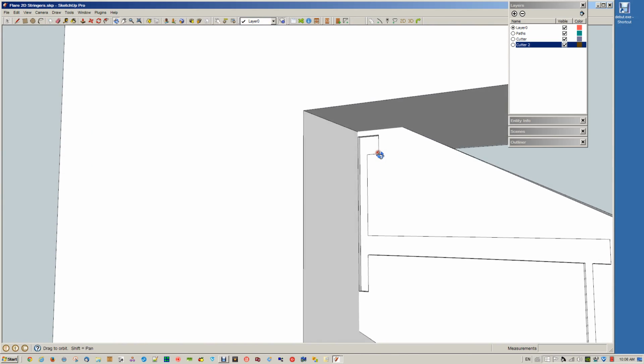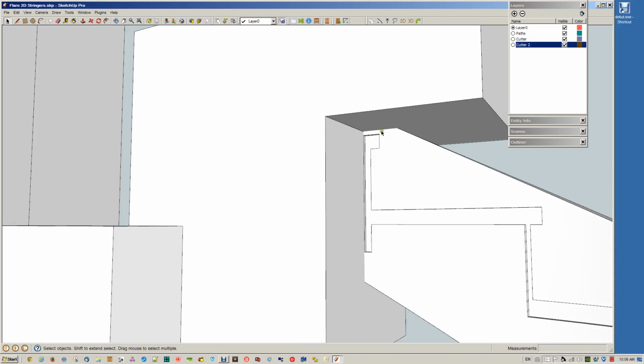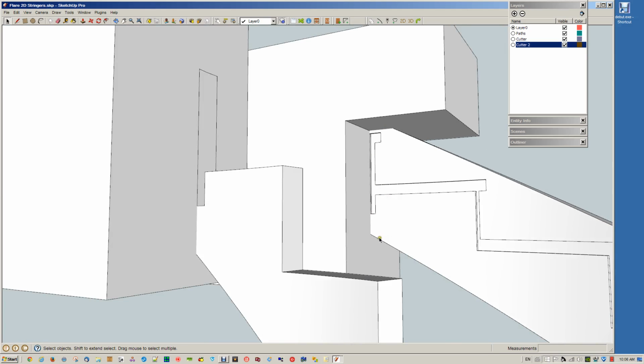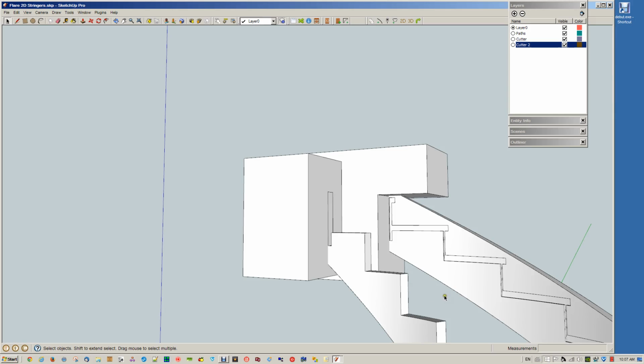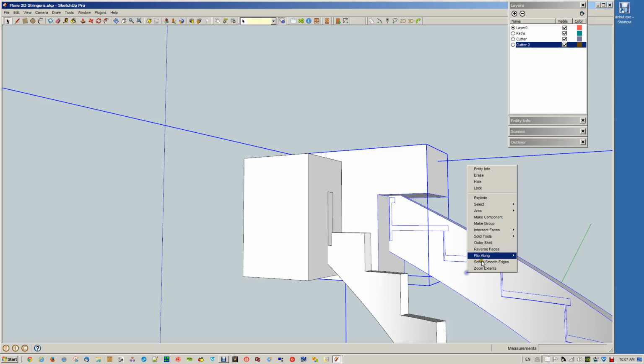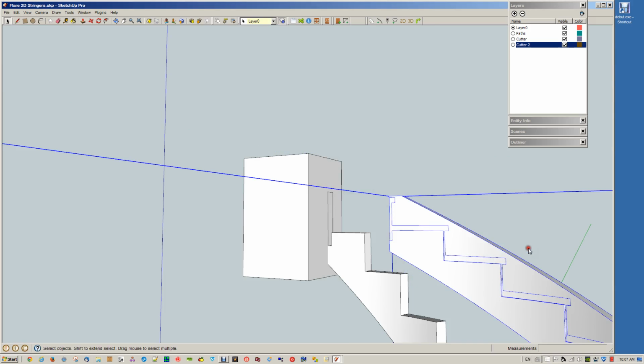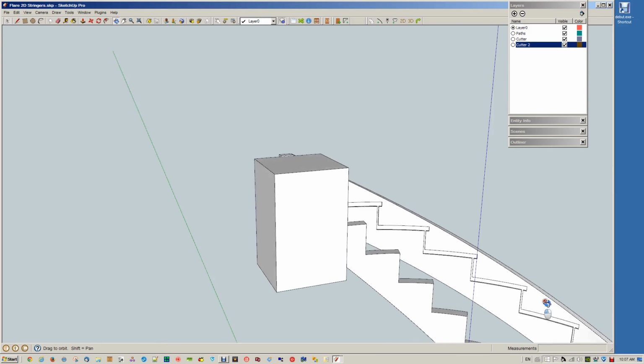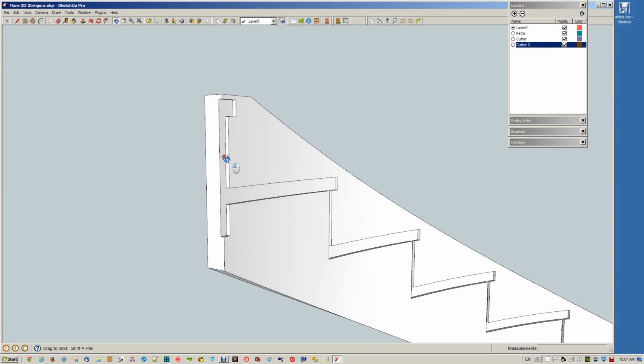What I wanted to have happening here is this finished part to come up 3/8 of an inch to allow for carpeting. And what I wanted to do is chop the stringer off. If we wanted the stringer to continue, we could change that and bring the bottom of the cutter up to the bottom where the riser board is, and it would cut it off nicely there too. But for now, this is good enough. Okay, so there is our routed stringer.